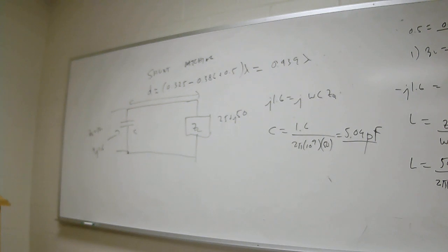What you have to do is get a picofarad capacitor in that ballpark, and then put what's called a variable capacitor near it, in parallel with it, that you can adjust to tweak it down to the actual value. Just because the leads themselves, do you all know this? Have you been told this?